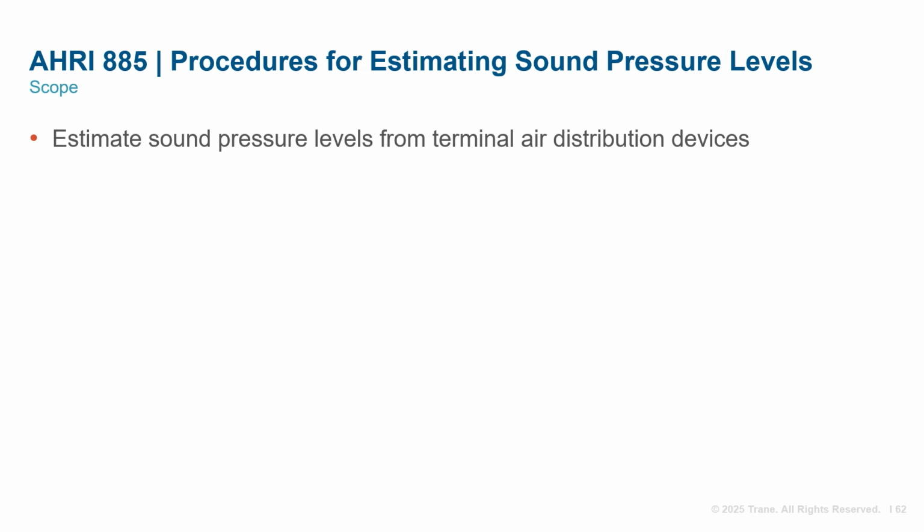Now that we've covered all of the indoor sound power standards, we will finish our discussion with Sound Application Standard, AHRI 885. The scope of the standard considers terminal devices, specifically VAV boxes. The calculations begin with standard 880 sound power values, functions for ducts, plenums, turns, diffusers, and rooms are provided. It essentially does on paper what Eric showed us using the Trane Acoustics program.